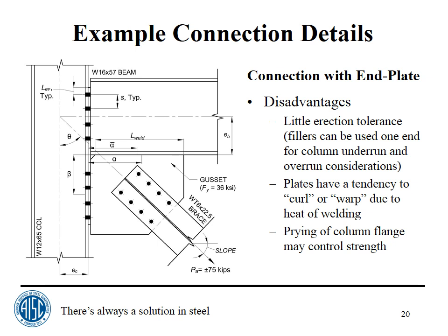No double clips, no end plates, no drilling of heavy columns. I mean, maybe we had to here and there, but we tried to avoid that, and we used shear plates almost everywhere. Okay, so along those lines then, the question is, of these 3 details, which is most economical? Your answer would be what? The shear tab, I think, is the most economic. I think it's the easiest to fabricate because you don't have to drill columns. You can avoid all this discussion of prying action.